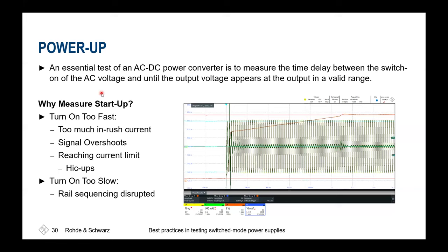certain manner so that the DUT is coming up in a well-defined way and is not already transmitting or trying to transmit something while the backend is not running and so forth. Therefore, it's also very important to know what the maximum inrush current is that I'm allowed to consume at the beginning of my chain of maybe many switch mode power supplies, and which overshoots shall be achieved at a maximum. So this is a complete system behavior test.